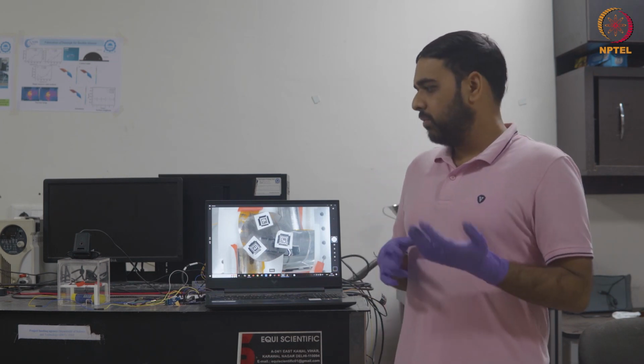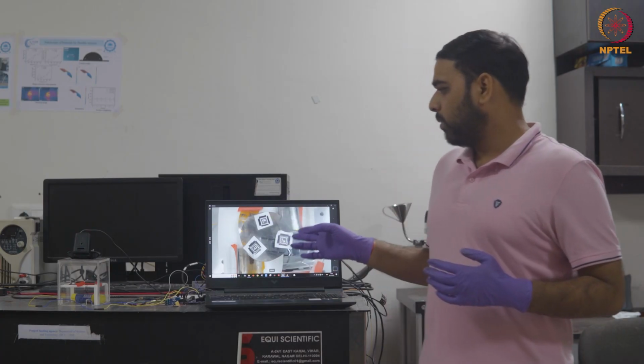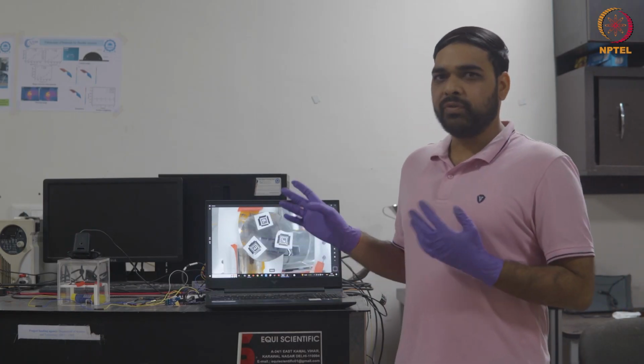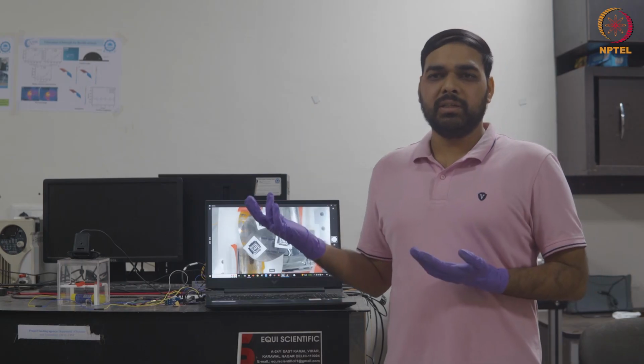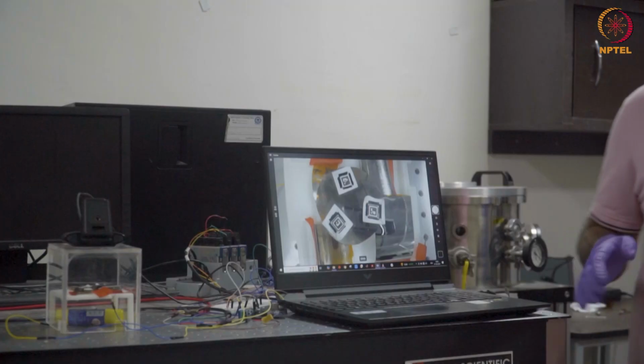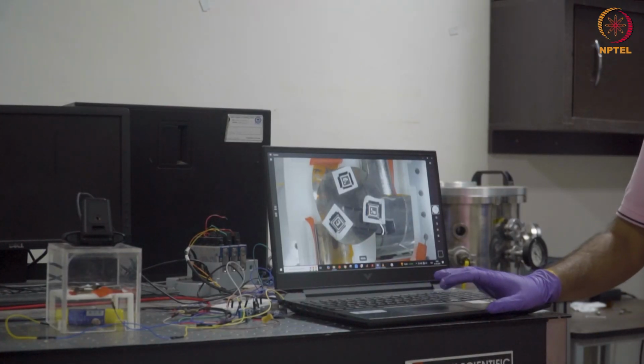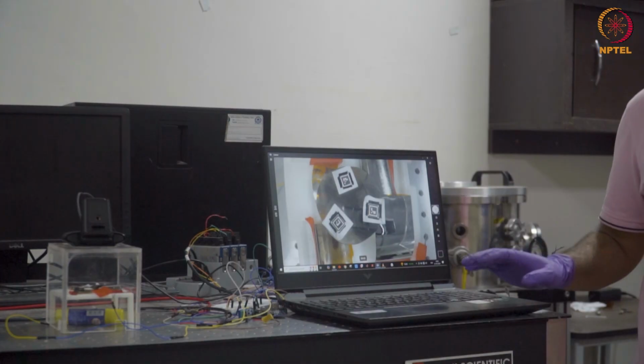So the shape memory allows thin film bimorphs that we have fabricated using different physical vapor deposition techniques, such as thermal evaporation or electron beam evaporation, that we can use in various applications such as the Stewart platform assembly that we are going to show here. Firstly, we cut different structures, such as circular or triangular structures, with the help of laser energy with laser micromachining, as we have also discussed previously. The same structures we use for fabrication of the Stewart platform assembly.